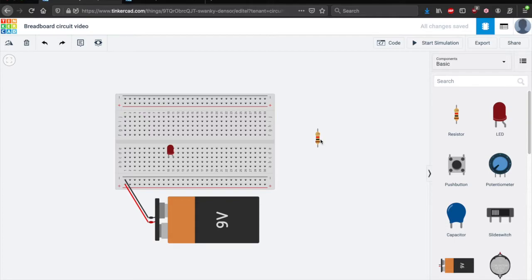Well, the real answer to that question is that if we only have the battery powering the LED and no resistance, because of how Ohm's law works, the current is going to be extremely high through the LED. That means the LED could burn out extremely quickly or could just blow up if we power it that way. We don't want that to happen. That's really dangerous, and if anything, our LED might just break, which is a waste of our time and money.